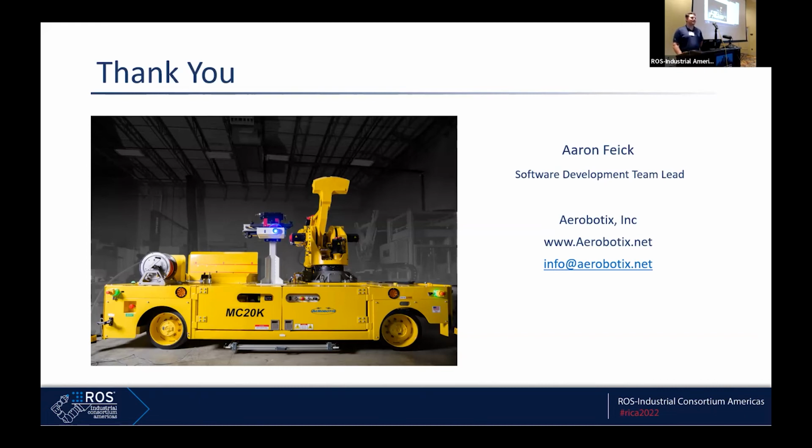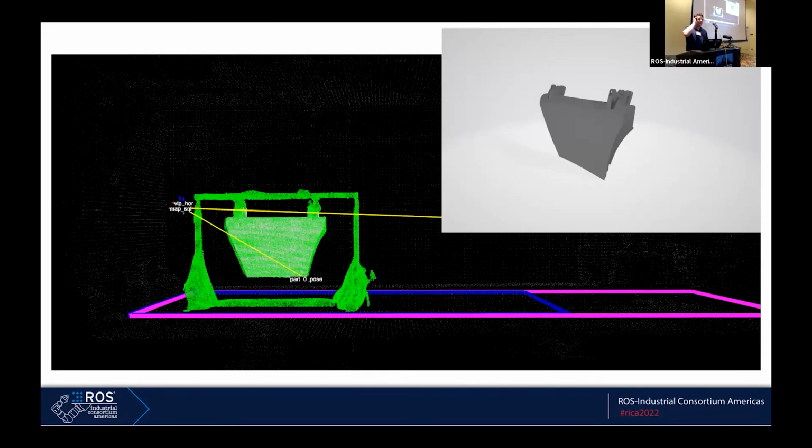You talked a little bit about your STL model registration. What about that alignment problem, especially with having the excess data? Yeah, so we did this in an interesting way. This implementation of the ROS setup was done through C++, so we went ahead and just added the PCL library side by side with it, so we could use all those ROS service calls in line with the PCL computations.